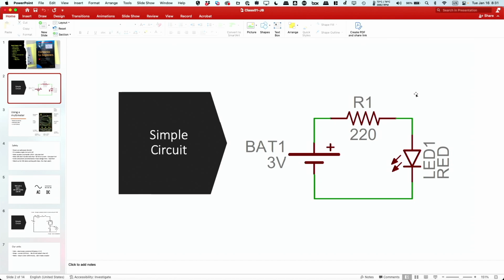The LEDs just happen to also produce light in the process, which is useful because we can make blinky things. But if we plug the LED in backwards, what's going to happen? Nothing. Yeah, it can't conduct current, so essentially you've put an infinite resistor there.